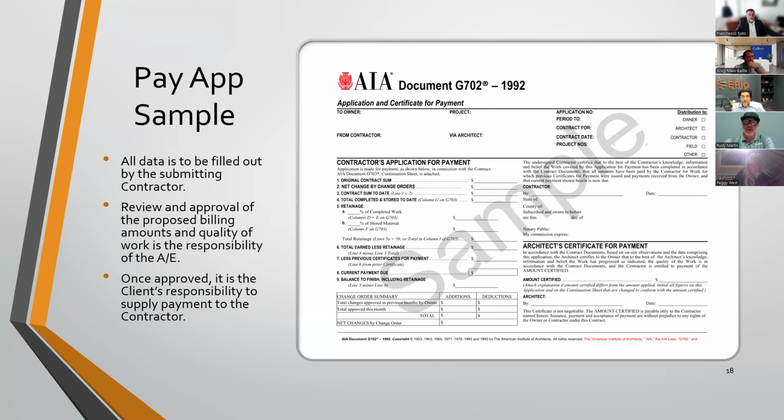You're trying to forecast every square inch of the building by only investigating 10 to 20% of it. Every square foot, we'll say, only investigating 10 to 20%. And that's because the cost to investigate every square foot of that building would be humongous. And even by doing so, you still wouldn't be right, because once we tap into that and we cut out that 1 square foot, it can go to 2 or 3 square feet based on the delamination that you didn't get from the acoustic sounding from that first point.